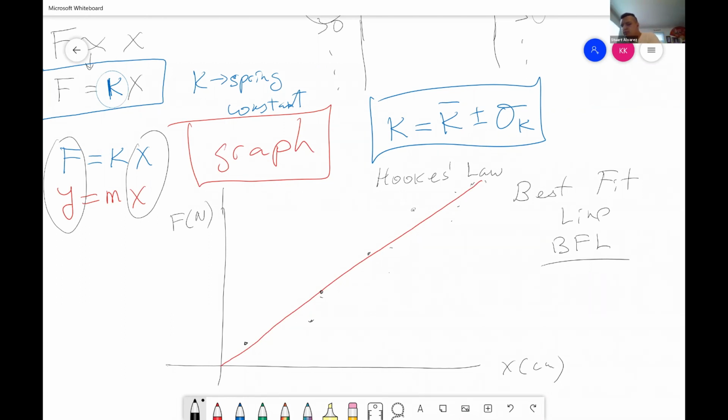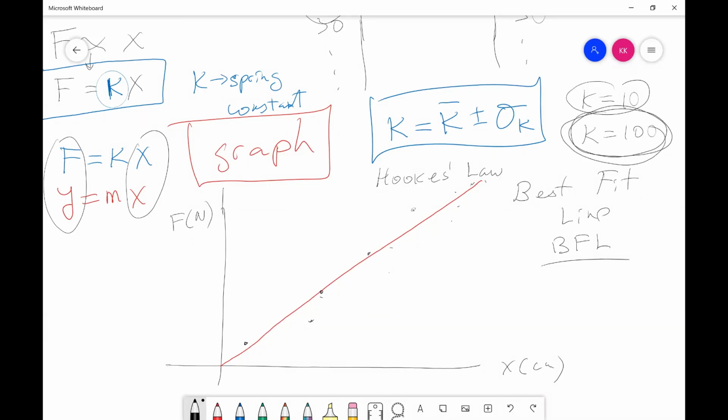Go ahead, Jenny, you had a question? So when it says K is spring constant, when you say spring, you're talking about the spring in your example, right? Yes. It's information about the property of the spring. So let's say, for example, when you have a spring that has a K of 10 compared to a spring that has a K of 100, this tells you that the spring that has K of 100 is 10 times stiffer. And if K is, for example, 1, that means it's a very loose spring. That means this K is actually information about the property of the spring itself.